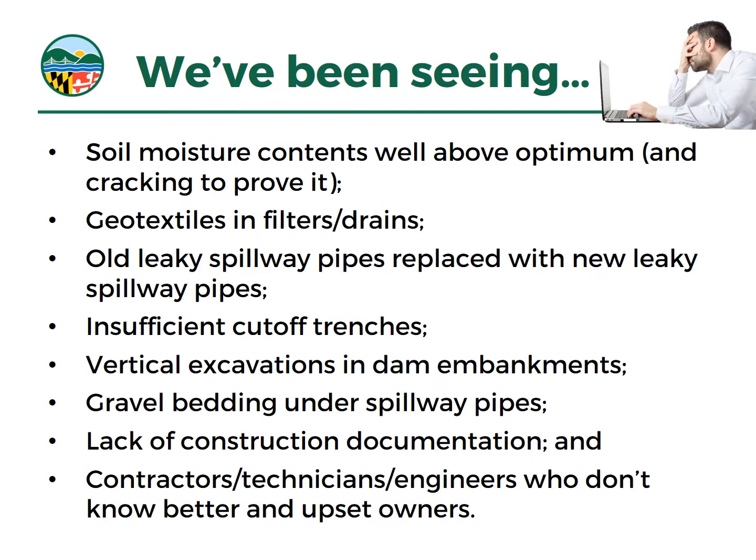That highlights itself in some of the submittals we've been seeing in the Dam Safety Division, or that we have been asked to review from a soil conservation district or other delegated authority. We have as-built plans coming in with reports of soil moisture contents well above the optimum. And people are saying, well, I met 95% compaction. But that's not the whole story. That's not all that's important. We've seen some incredible slope distress because of soil moisture content issues.